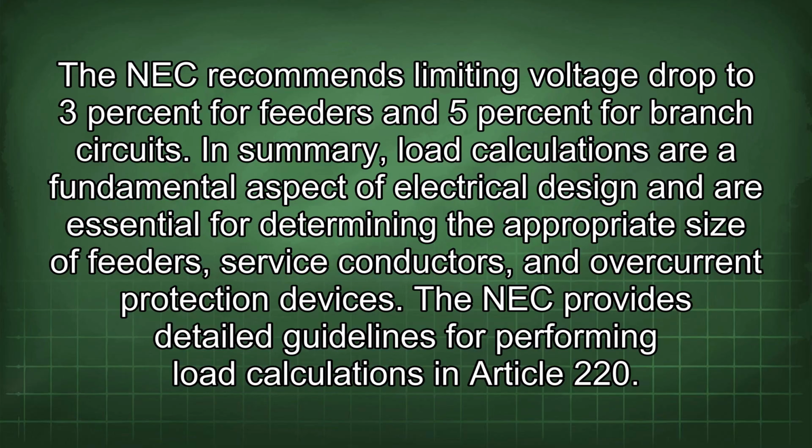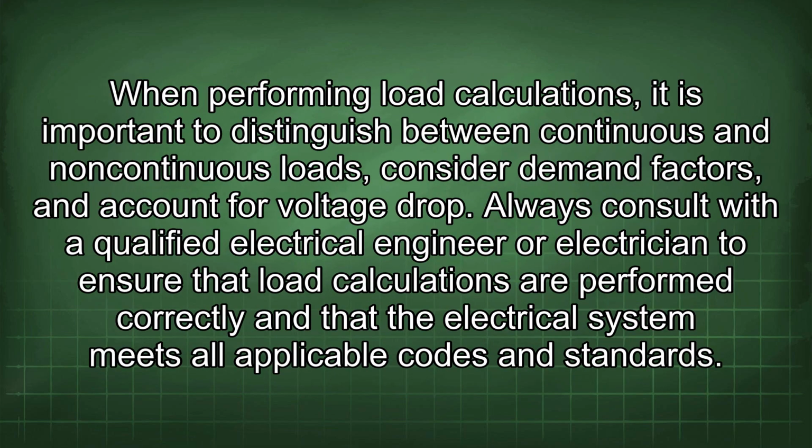In summary, load calculations are a fundamental aspect of electrical design and are essential for determining the appropriate size of feeders, service conductors, and overcurrent protection devices. The NEC provides detailed guidelines for performing load calculations in Article 220. When performing load calculations, it is important to distinguish between continuous and non-continuous loads, consider demand factors, and account for voltage drop. Always consult with a qualified electrical engineer or electrician to ensure that load calculations are performed correctly and that the electrical system meets all applicable codes and standards.